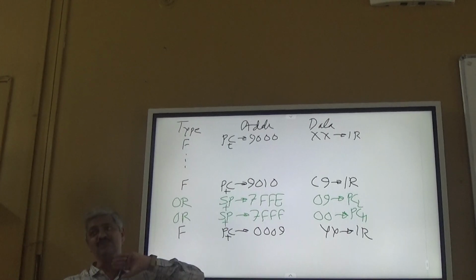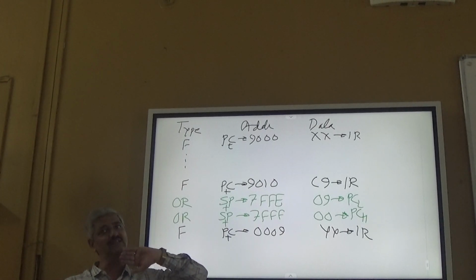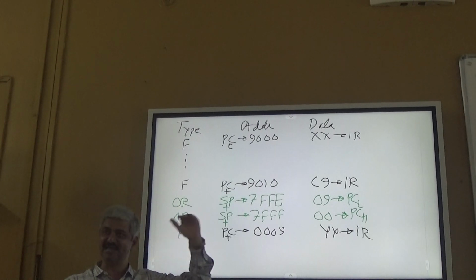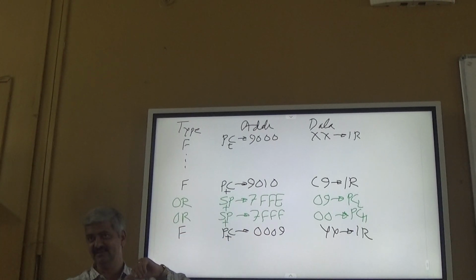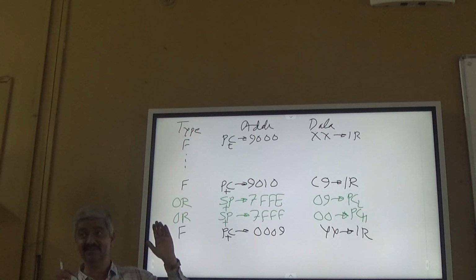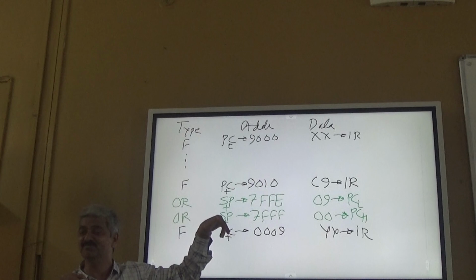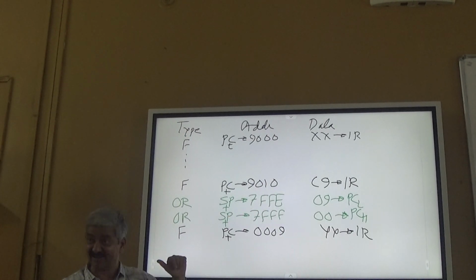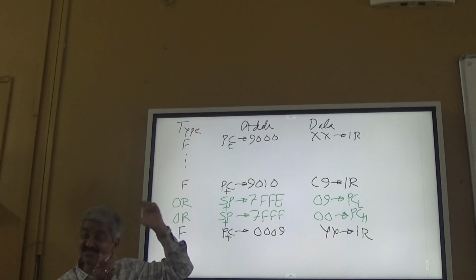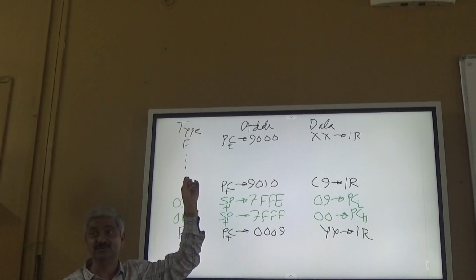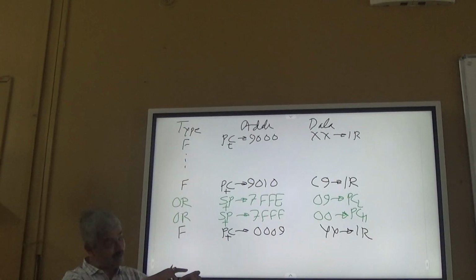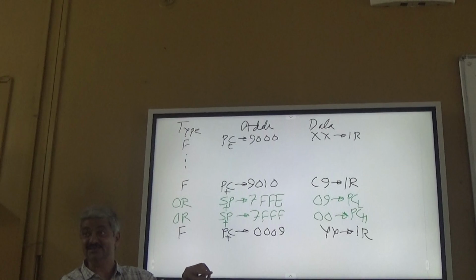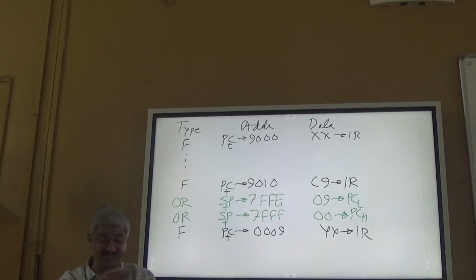The subroutine multiplies HL and gives me HL. If that is the only thing I know, and I am using register A and register B for some purpose, I call 9000 and it returns, HL contains the result I want. But if B was being used for some purpose, and after the subroutine I start using B again, B has been changed, right?